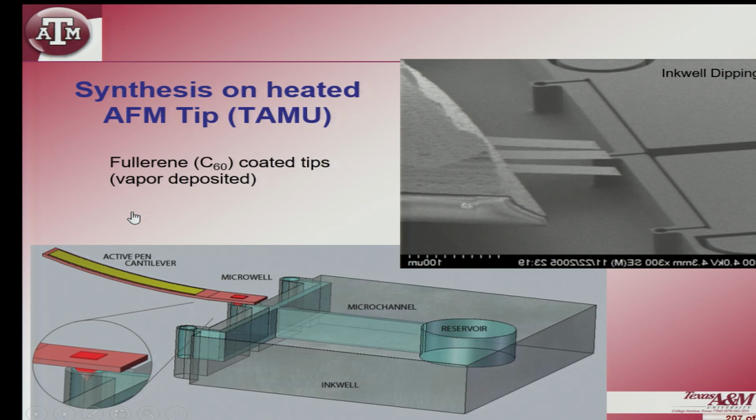Okay. And normally, because this is gold and silicon they form a sort of a composite called gold silicide, and that happens at about 300 degrees Celsius. And so, we know our heater for sure fails at 300, because at 300 degrees Celsius it forms the gold silicide, and once it forms the gold silicide, the heater becomes non-conducting and the whole thing fails at that point. Okay. So, we know for sure that the system temperature never exceeded 300 degrees Celsius.